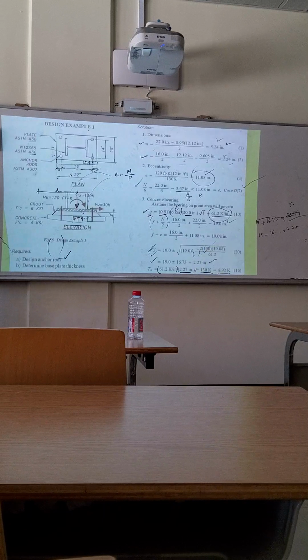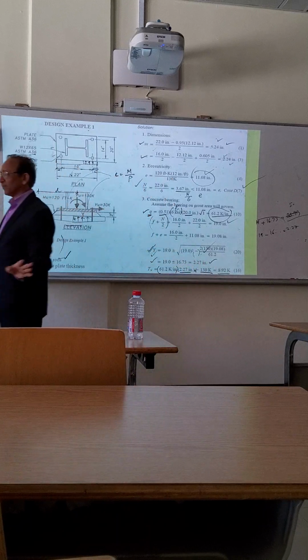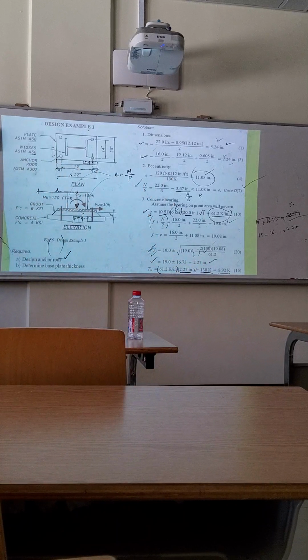Total force of tension you have seen is only 8.92 kilopounds. Now you decide how many bolts you will be providing, and for that you decide the capacity of one bolt, and then that will be deciding how many bolts will be required.